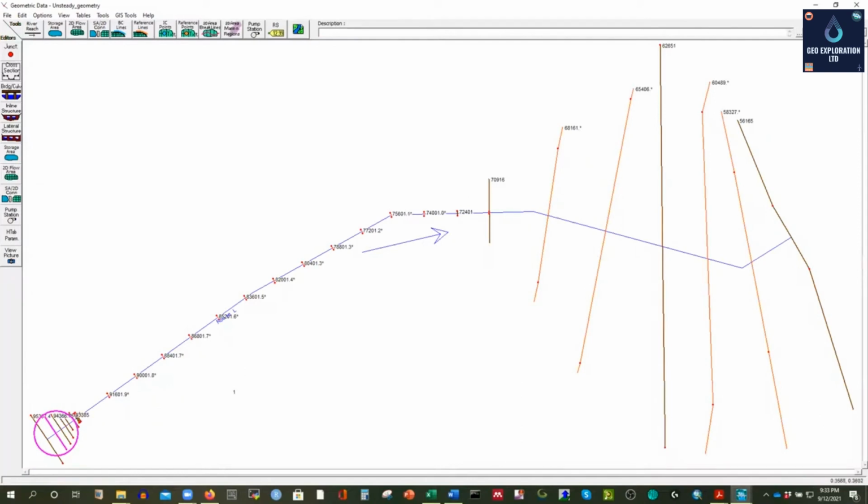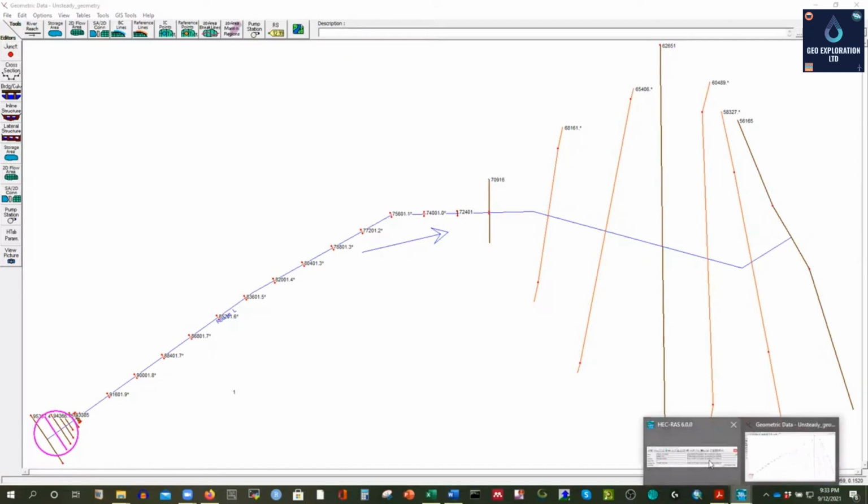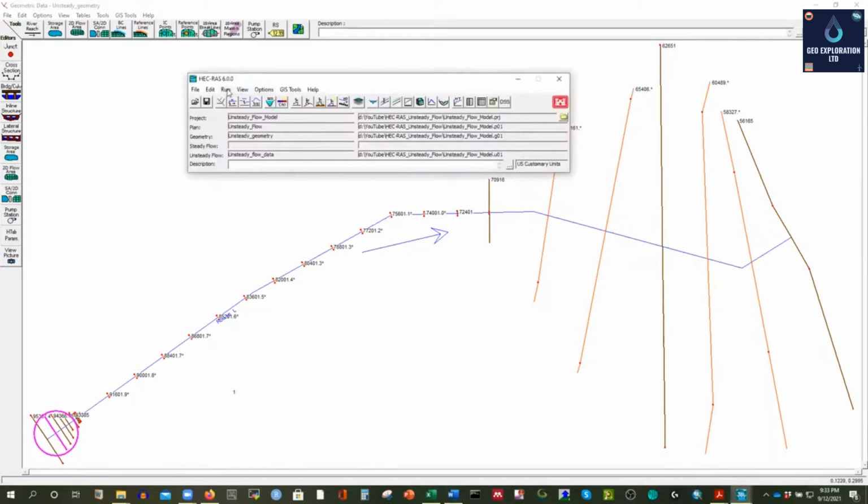And last, I'm going to show the effect of time step. That is what I was trying to say, what will be your time step. You have to reduce the time step to improve the accuracy of your model prediction. For this condition, we have our observed data, and we'll check with it. I'm not going to do that here right now. I'll do it for the sediment transport model. We have our observed sediment density, and we'll check if our model is working or not. That's why we'll calibrate our sediment transport model, because we have our observation data.